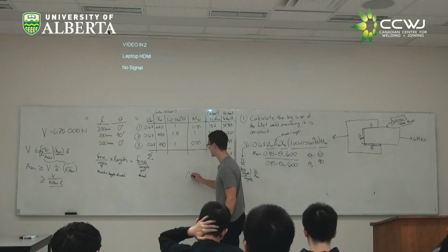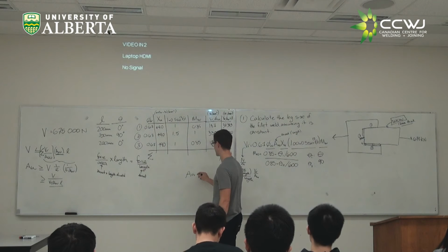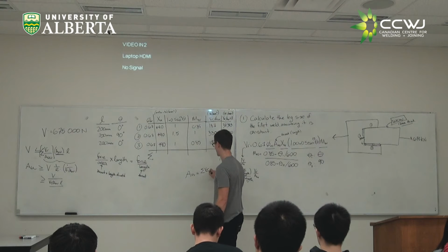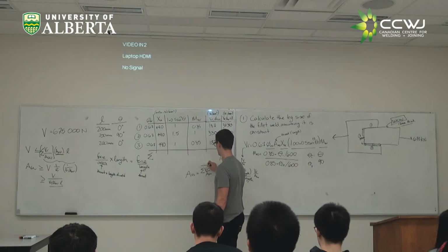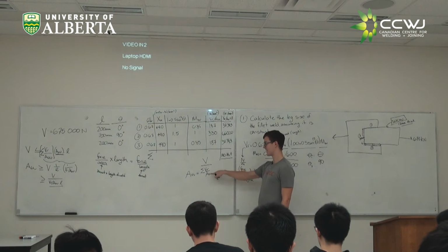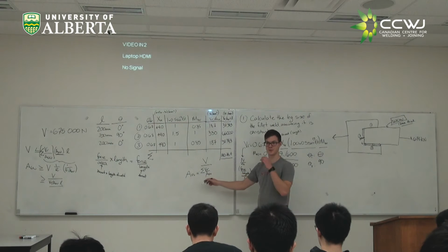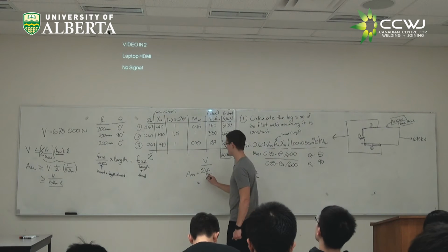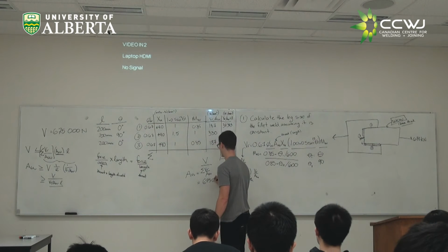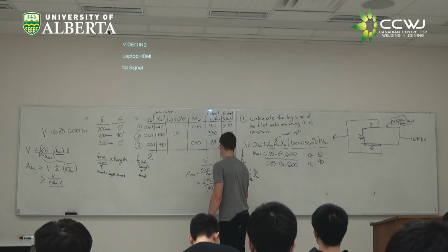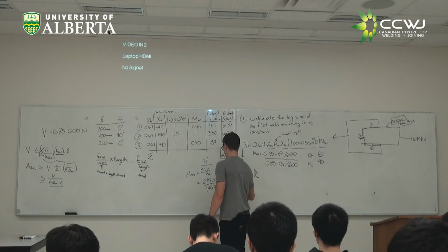So if we want to get AW and we have VR, we're going to take our sum of VR over AW, right? If we take V divided by V, sum of VR over AW, we're going to end up with our units of length. That's going to give us our weld size. So if we sub in, we've got 675,000 newtons over 140, 784 newtons per millimeter.